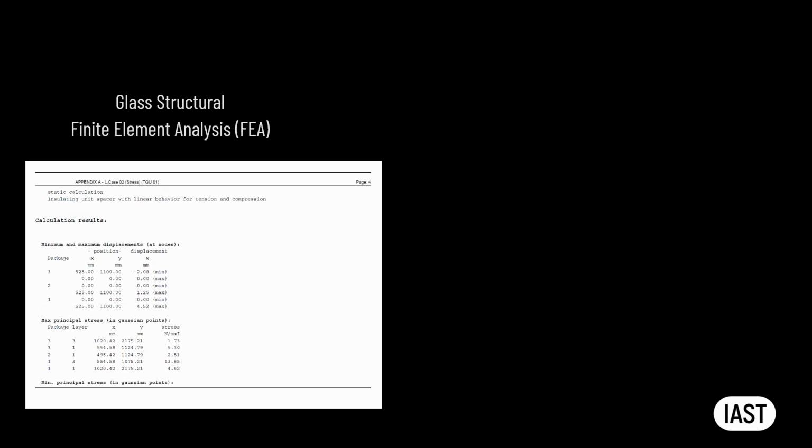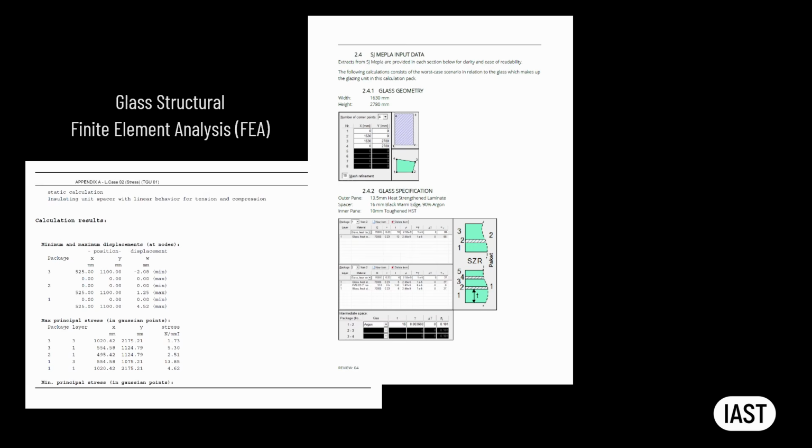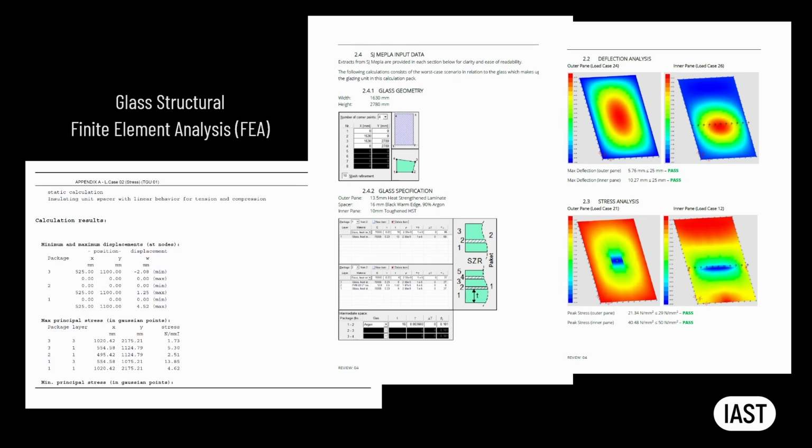The facade specialist contractor and facade consultant are expected to perform structural finite element analysis to verify thickness and thermal treatment of the glass panes, while the glass processor is expected to conduct thermal safety analysis to verify whether the selected glasses are strong enough to withstand thermal shock. The glass used should be safe for both occupants and the public.